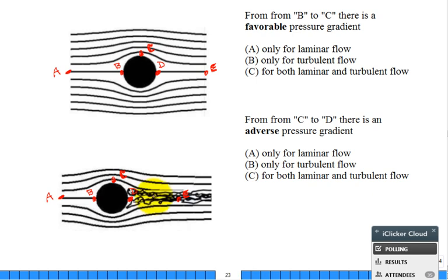And so in this wake region, you get not good. I mean, you don't use Bernoulli's equation in that wake region. You violated one of the requirements of Bernoulli. What was the one? Along a streamline, inviscid. So there's some limitations to Bernoulli's equation. But you don't get perfect pressure recovery. You start to get a pressure over here that's low compared to the stagnation pressure, which is high.